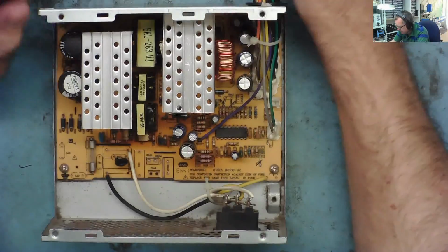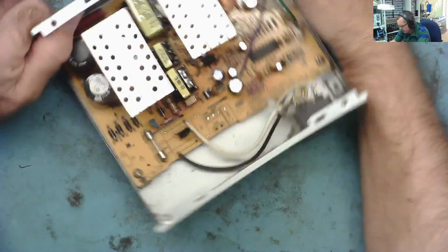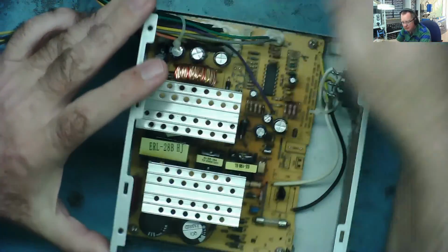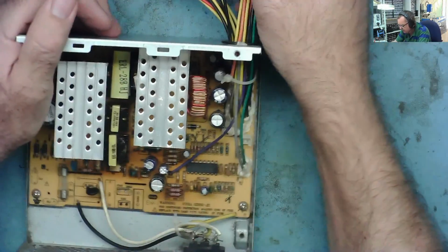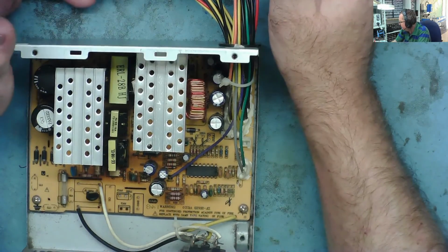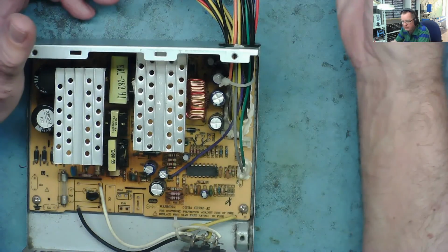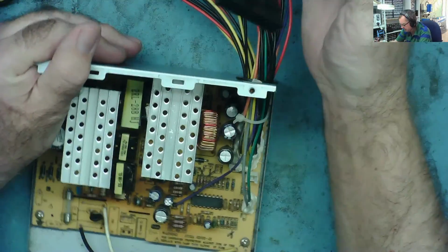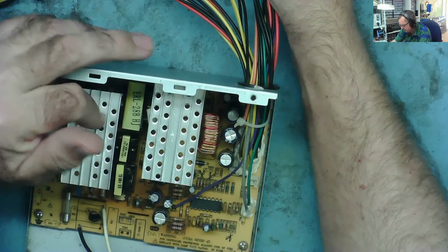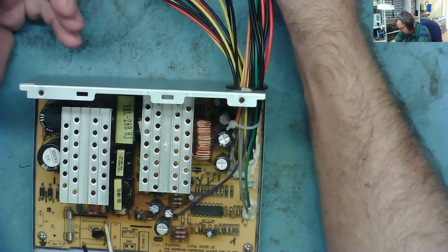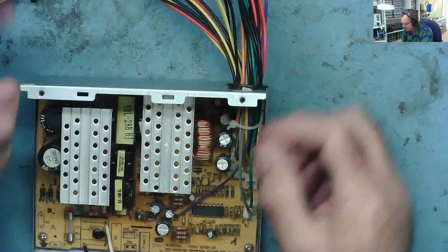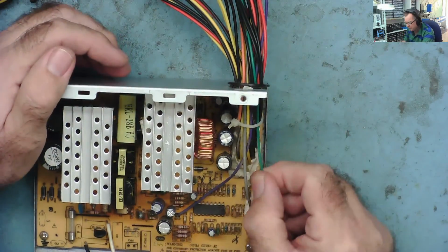Right, so I've had a think about it. Yeah, I think I can do this. So this is an old ATX power supply. It does work. It actually has a bulge capacitor over here, but I'm not too bothered about that at the moment. And I've got the bench power supplies, so I can send 12 volts, 3.3 and 5 volts into this lot from my bench power supply. I'm thinking I can use this just to generate the -12, because I don't have that from the bench power supply, and to do the 5 volt standby. And this green wire, when it grounds, it switches on, so it switches the -12 on.